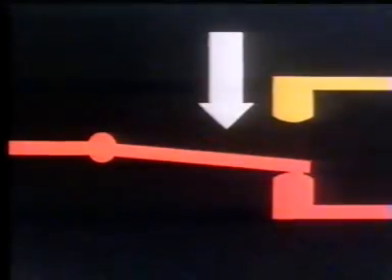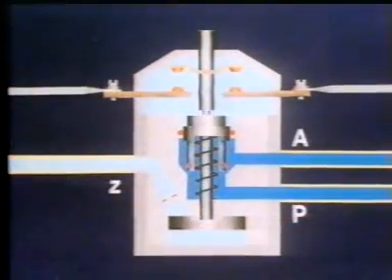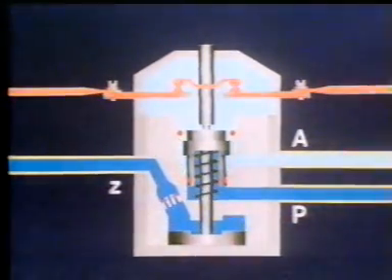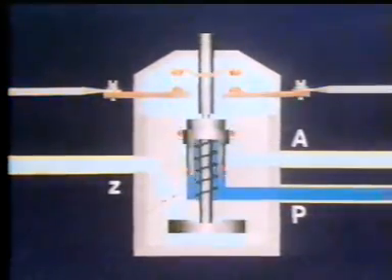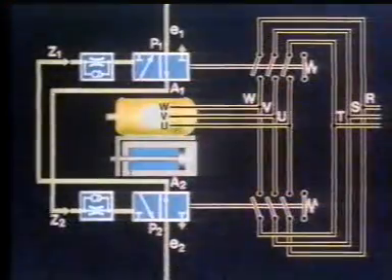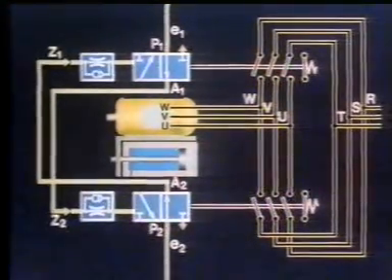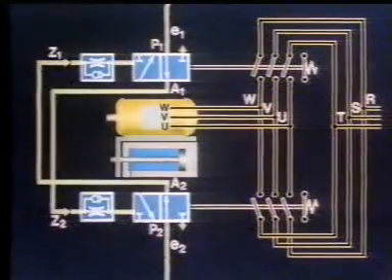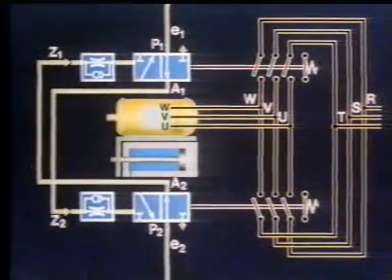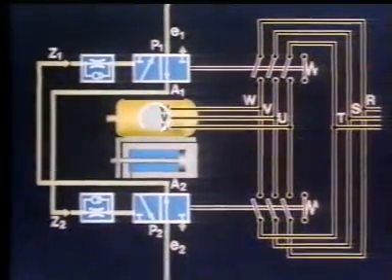In summary, pneumatically operated switches can be designed as normally closed, normally open, or changeover switches. Pneumatically operated contactors save on the switch when actuating electric motors. In a reversing contactor combination, pneumatic interlocking is possible. In this way, simultaneous signaling for clockwise and counterclockwise operation is impossible.